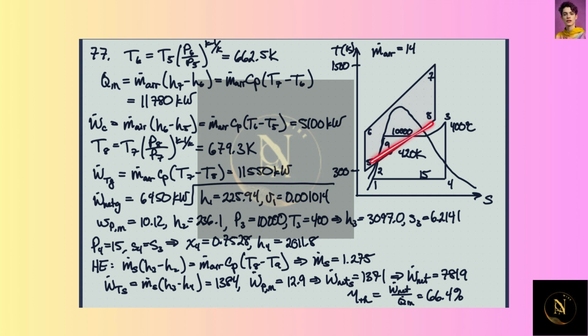the hot exhaust gases. Basically, in this cycle, we're just pulling in new air all the time. So this is not really a process from here to here. We're just extracting the heat as it comes out from here. It's not a closed loop for a gas turbine because we're just using air as the working fluid. In the steam cycle we almost always have a closed loop here, although we wouldn't necessarily have to.